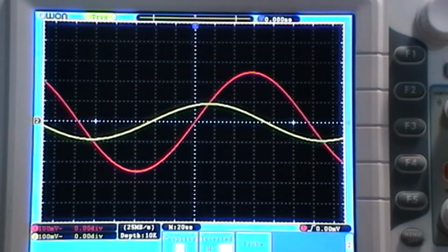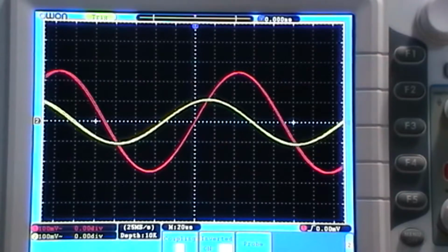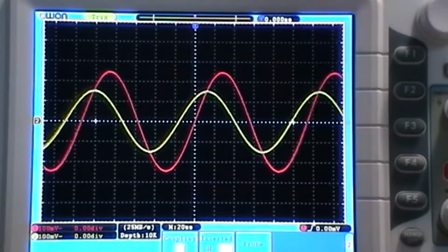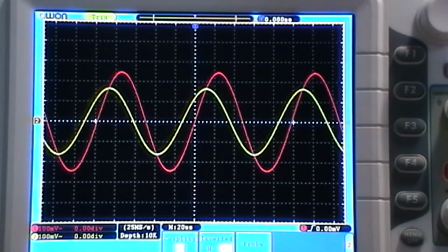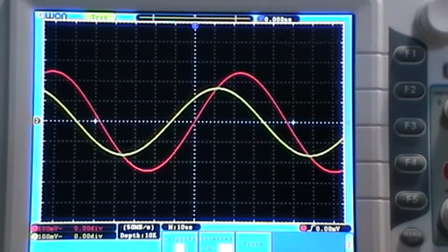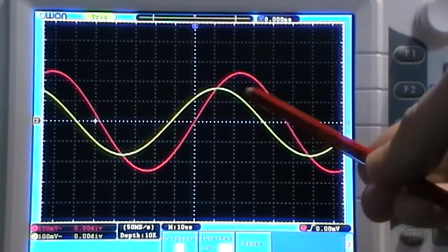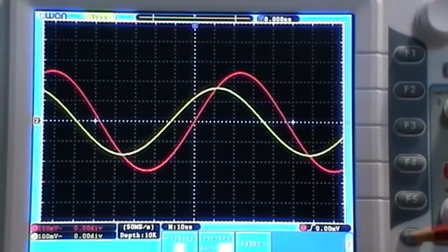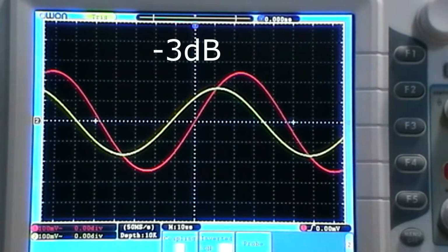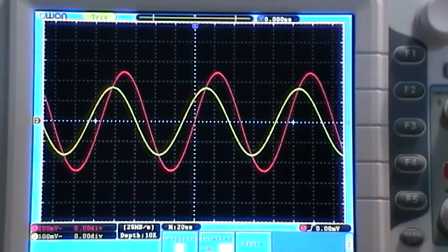So as you can see, I'm getting a lot more coming through, and I take it to 10.6, haven't I, to find my cutoff point. 10.6, there we go, at 10.6. Again, it looks just like the other frequency signals that we were looking at. We've got about -10 dB, same phase shift, but we are at 10.6 kilohertz now. Massive amount of frequency above what we were dealing with the higher capacitance.